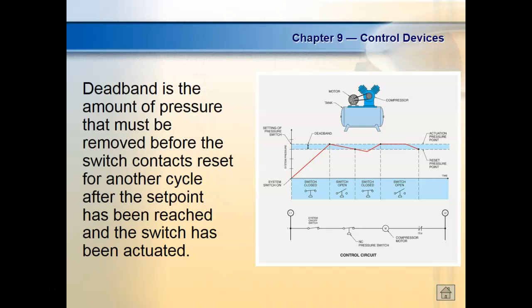So once you hit 100 psi, around there, what happens to the motor? Cuts off, and then you're out there using your tools and stuff like that. And then, compressors are rated at two different things. What are the two things we rate compressors at? Feet per minute, CFM, and that gives you the flow rate, how fast things are going to move. So how fast the fluid moves determines the speed. The pressure determines the force.